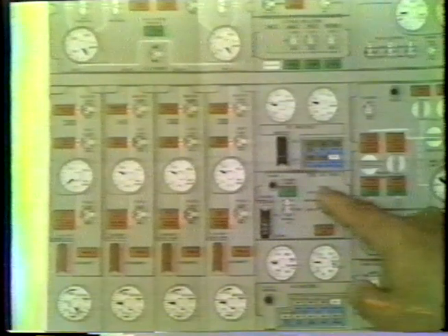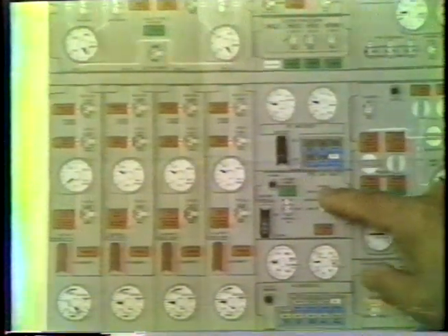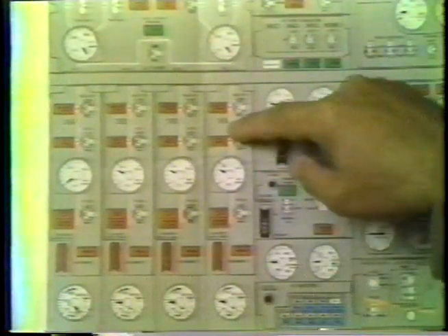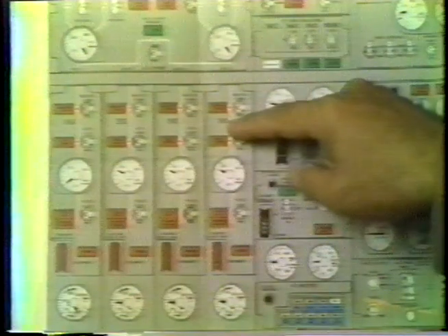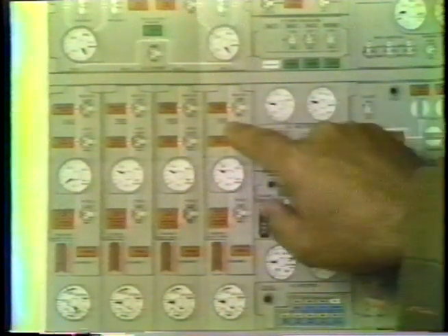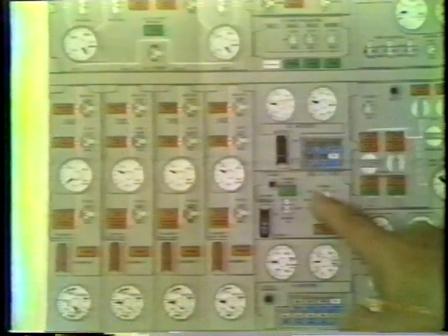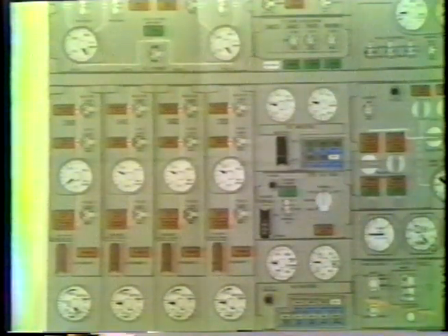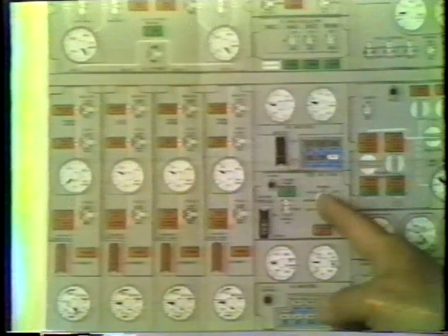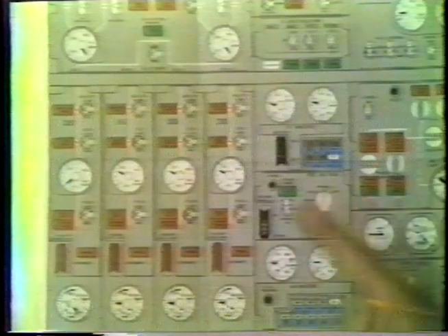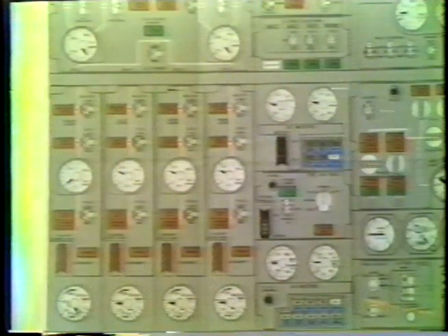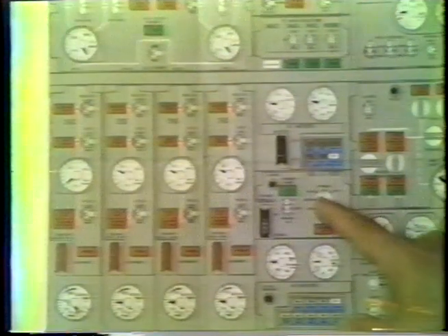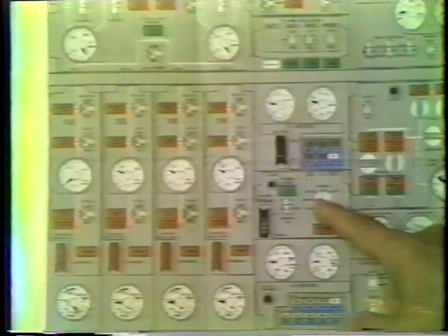Essential power in normal can be fed from any one generator through the tie bus, or directly from bus number 4, from generator number 4, or from ground power, or from APU power, without moving the selector switch. Under normal operating conditions, essential AC power should be available in the normal position unless you have loss of all generators. No need to switch essential power as you switch types of power from ground power, APU, or aircraft power.